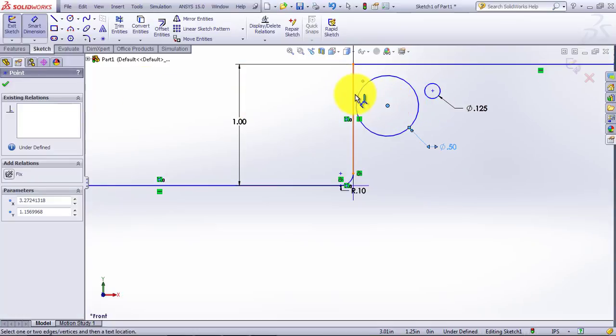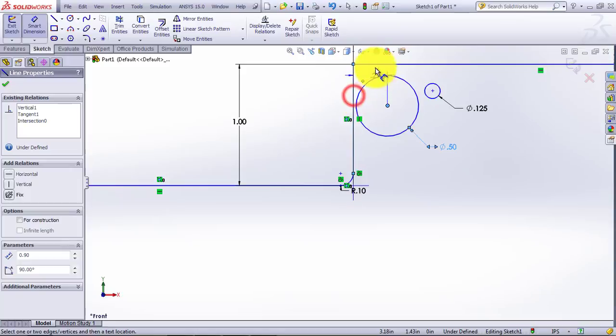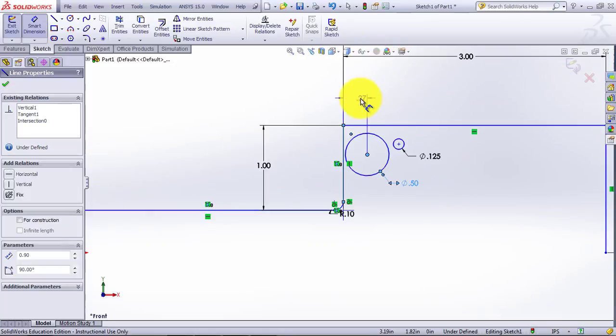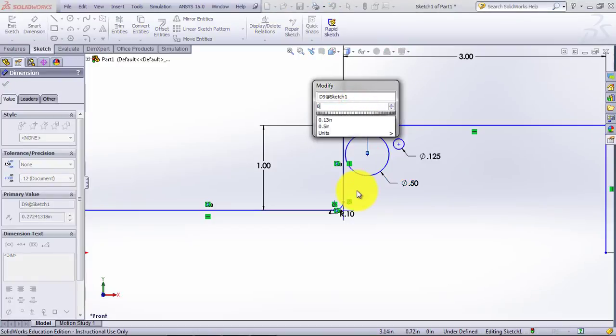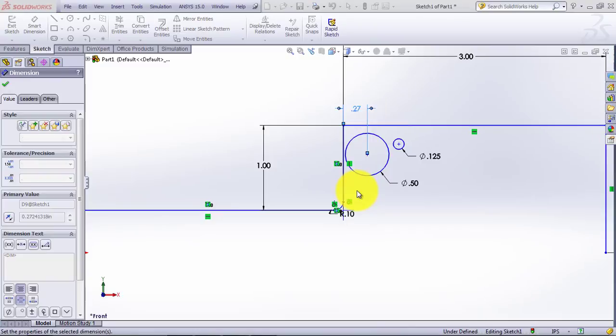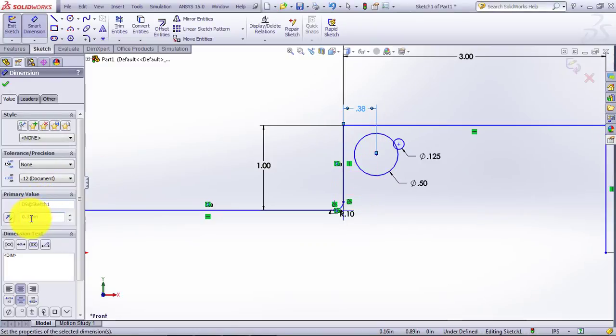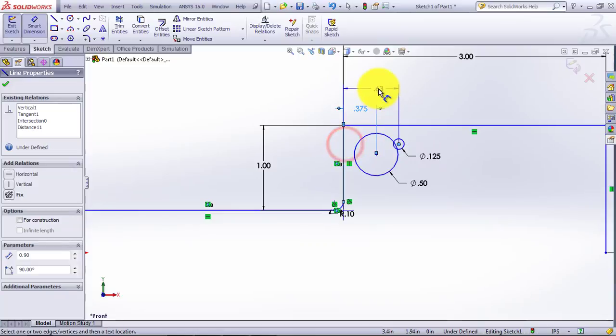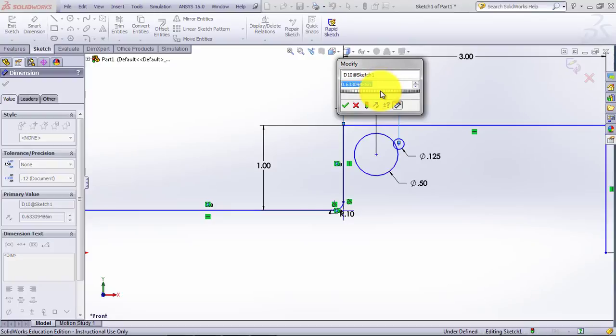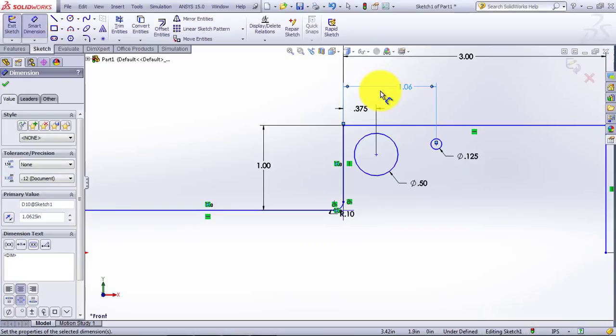We'll click there and here. And I should probably zoom out a little bit. So that looks good right about there. And that one is 0.0375, 3/8 of an inch. Oh, and that one's kind of hidden there too, so let's go 3 sig figs there. That looks good. All right, let's go do the circle so it doesn't get out from underneath the other one. And that one is at 1.0625. All right, and so the sig figs there.